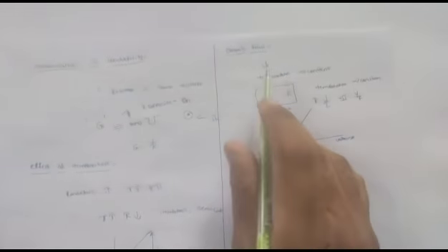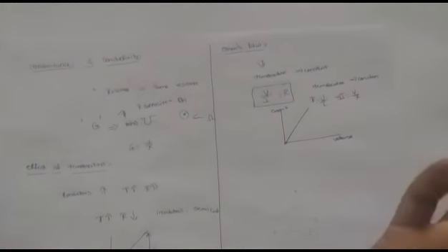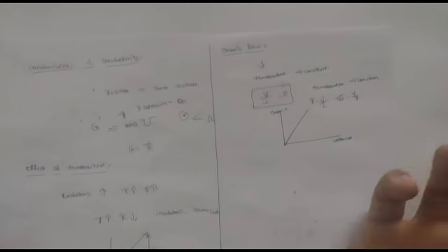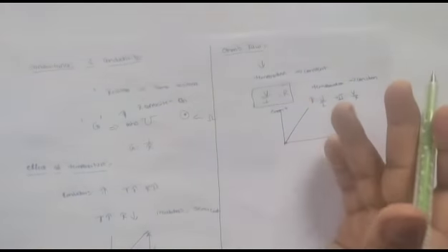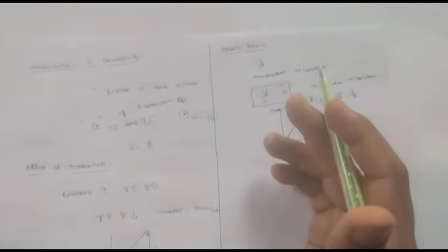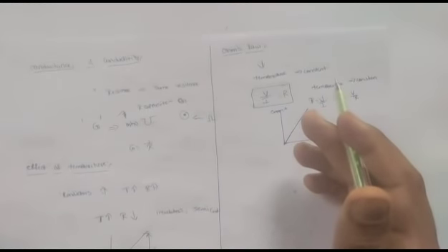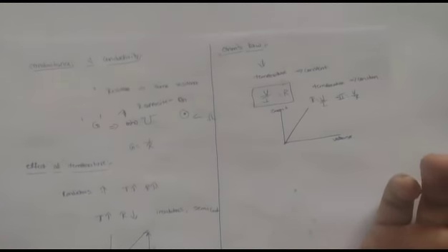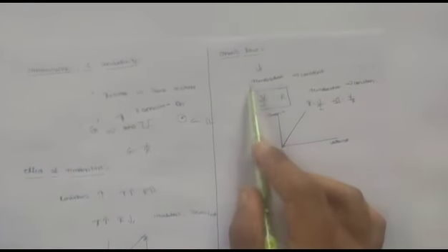This Ohm's law is not applicable to temperature changing materials and also non-linear materials like carbon, thyrite and electric arc, etc. Also for semiconductor devices, this law is not applicable. In the same way, in vacuum tubes and gas filled tubes, it is also not applied. For electrolytes and ionized gases with electrodes, it also cannot be applied. And in arc lamps also it is not applicable. So that's it. This is the basic about a quick Ohm's law.